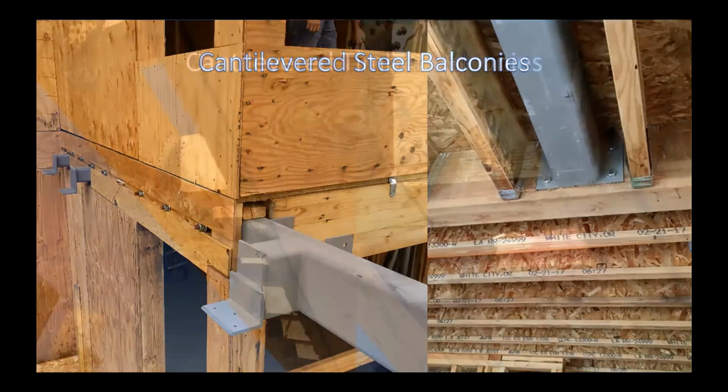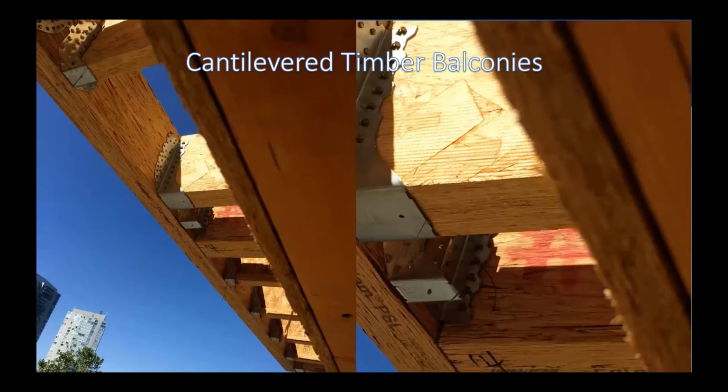But there's a lot of cantilever timber balconies as well, and they often reverse the hangers into different directions, up and down, depending whether they want to take uplift or down direction, to transfer the load from a perimeter beam back into the building.